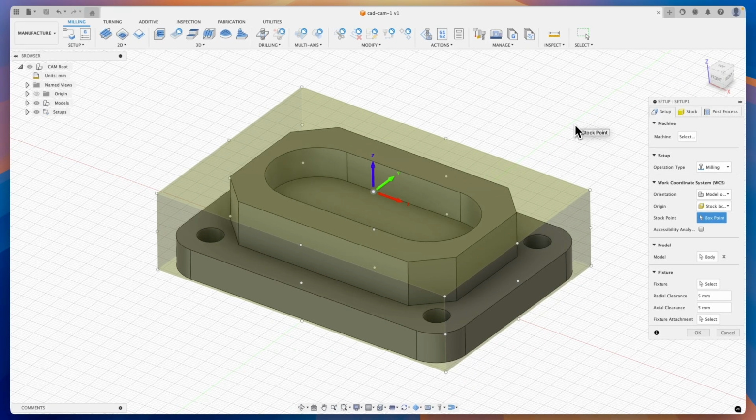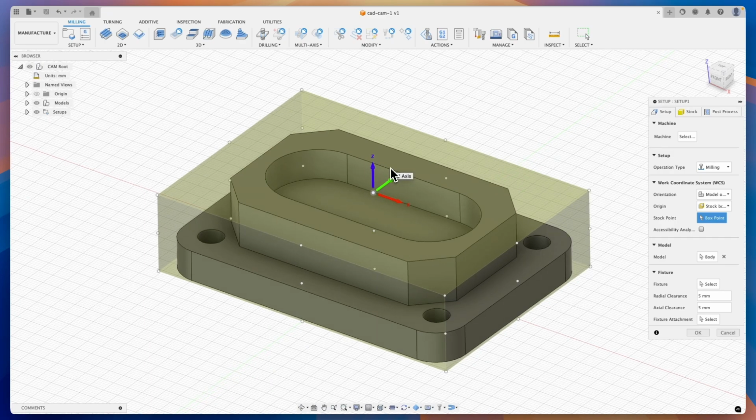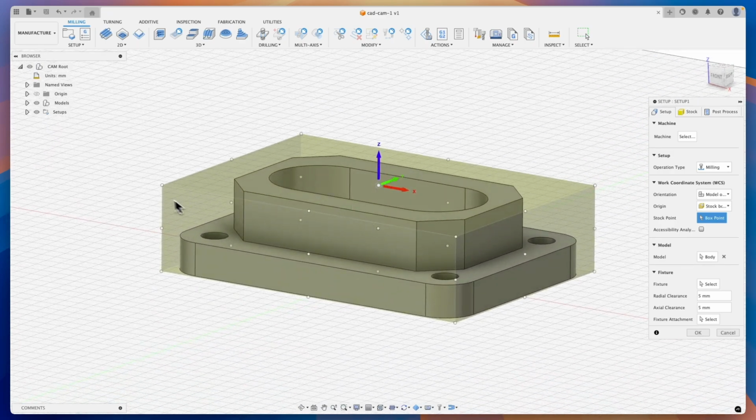This is a fairly important step, as later on the machine we should place the origin of the coordinate system in the same location on the workpiece. If here, during the preparation of the machining program, the origin is in the center of the workpiece, and on the top surface, we should place the origin in the same place on the machine, we will leave the origin here. As you can see, we have 27 specific points where we can place the origin.